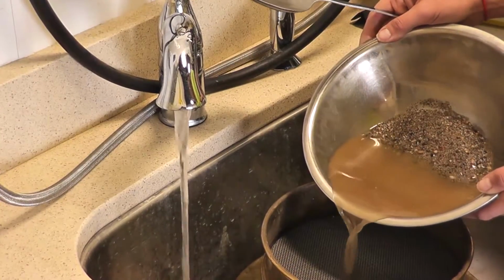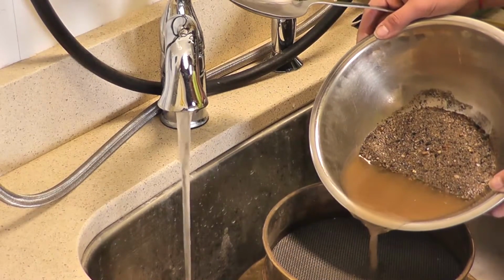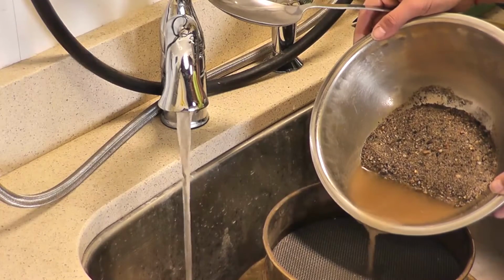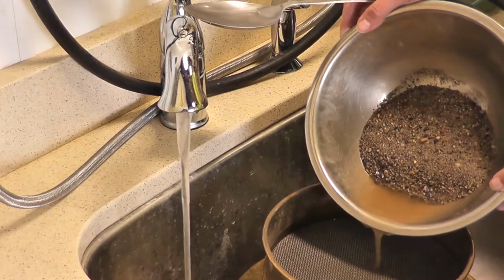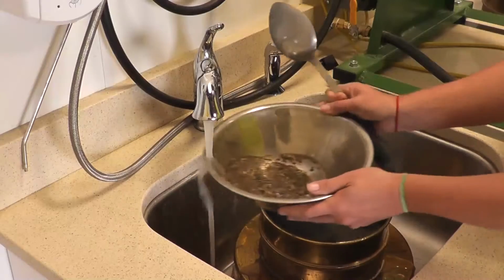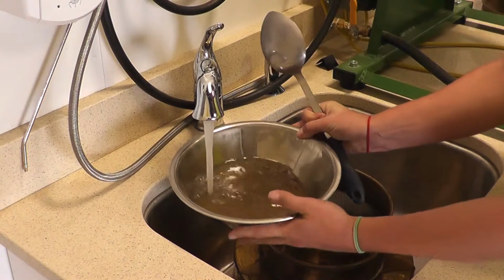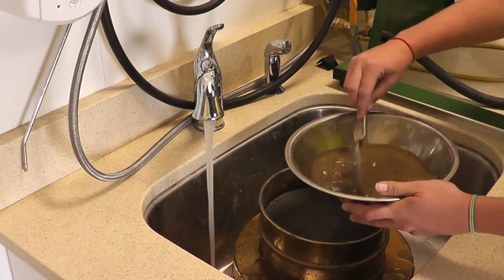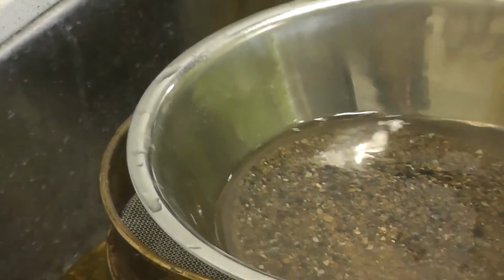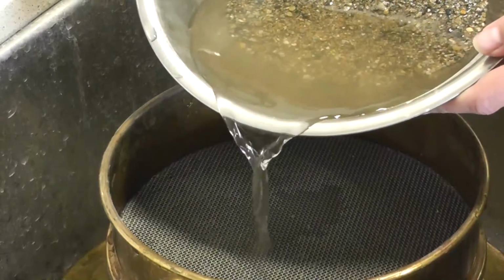Carefully pour the water and suspended fine materials over the nested sieves. Dispense only the water with the suspended fines and not the sample itself, as that could damage the sieve cloth. Repeat adding the water, agitating and washing the sample several times until a majority of the suspended fines have been washed through the sieves. The washing process is completed when the wash water containing the fines becomes clear.